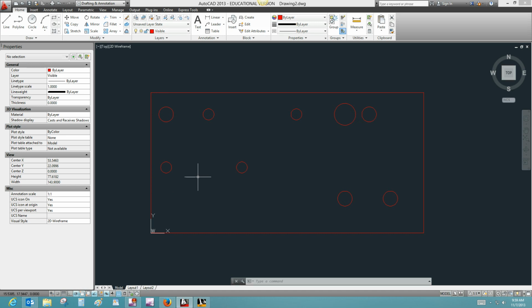So I have my dynamic input turned on. CP, enter. So relative to the center point of this, we need to go right, which is positive along the x-axis, 14, and then down 10. So that'd be negative 10 on the y-axis. Okay. And let's just verify that coordinate. It should be absolute coordinate 19, 11, which it is.